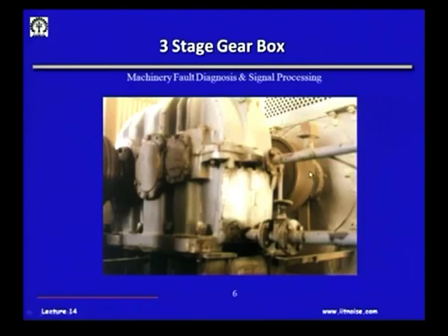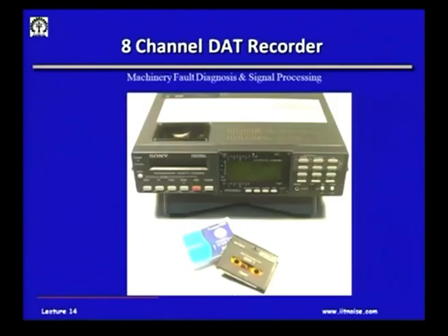Because of obvious reasons, there are certain defects. So, we put accelerometers at the bearing locations and accelerometers near the foundations, and we took the measurements of these vibrations simultaneously. Obviously, this analysis, as I was telling you, Cepstrum cannot be done real time on the fly. So, we have to record the signals in a DAT recorder, wherein you can record almost 8 channels of vibration simultaneously to a bandwidth of 20 kilohertz.